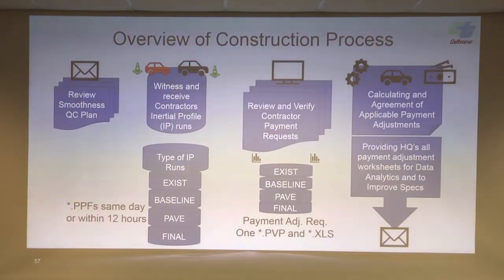Okay, so now I'll go over an overview of the construction process. I'll be going through every one of these: review the QC plan, witnessing the quality control, witnessing the inertial profiles, reviewing the payment request, and then calculating an adjustment. And at the end, basically we want to get all this data submitted.